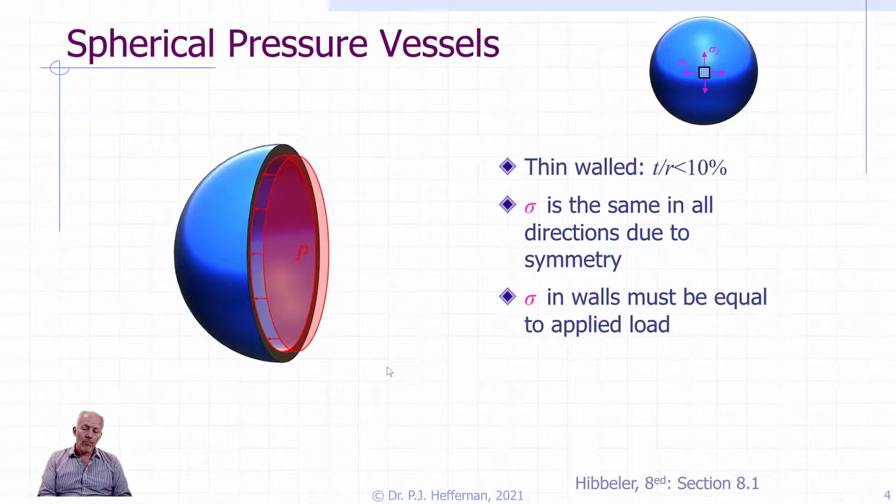So pressure always acts normal to the plane and constant over its area. So we have this pressure, and we can see in this case, because of our cut plane the way it is, it's going to be acting to the left, constant P, over that entire surface area. So we can figure out what the forces have to be restricted or resisted by the pressure vessel itself.